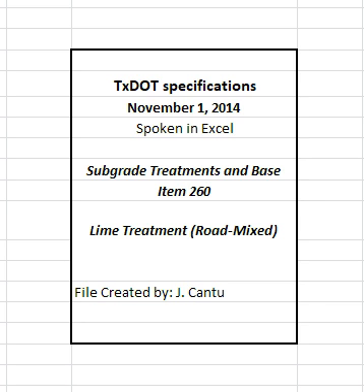Begin rolling longitudinally at the sides and proceed toward the center, overlapping on successive trips by at least 1/2 the width of the roller unit. On super elevated curves, begin rolling at the low side and progress toward the high side. Offset alternate trips of the roller. Operate rollers at a speed between 2 and 6 miles per hour as directed.